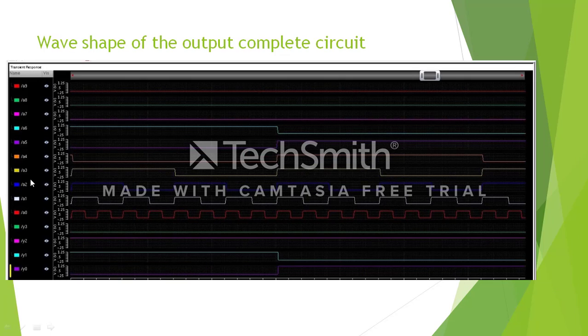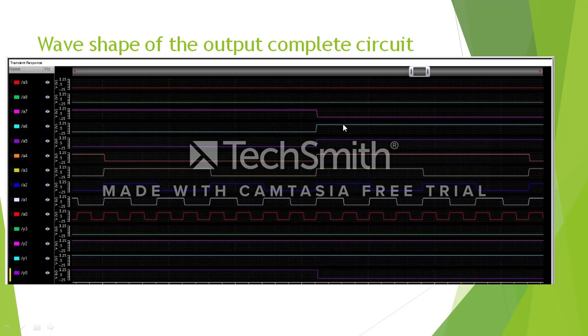And in this wave shape, we can see that when our input pin A5 is high, then whether the input pin A0, A1, A2, A3 or A4 are high or low, the output pin will always show 0 1 0 1. So Y3, Y2, Y1 and Y0 are showing 0 1 0 1. Similarly for A6, the output pin is 0 1 1 0, and A7 0 1 1 1.